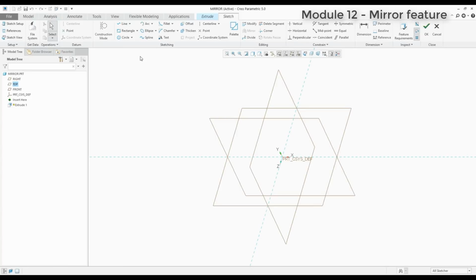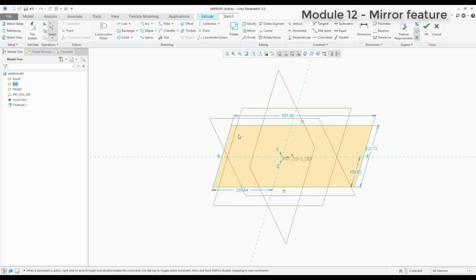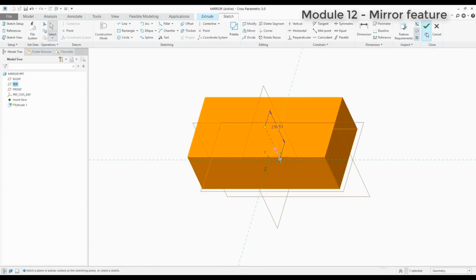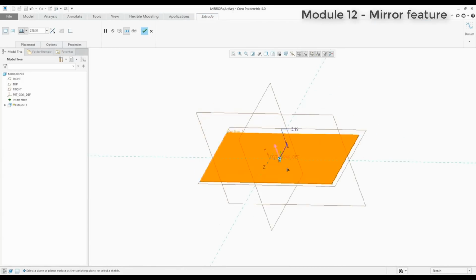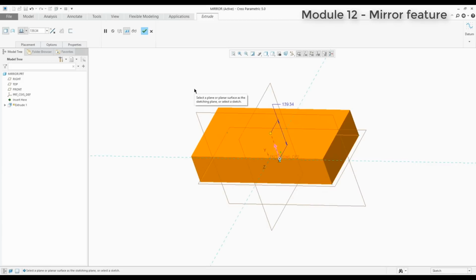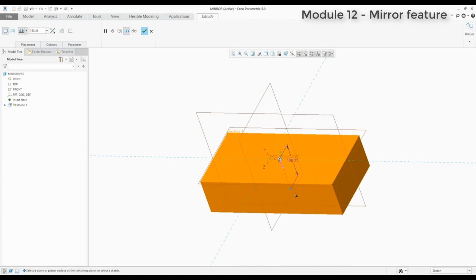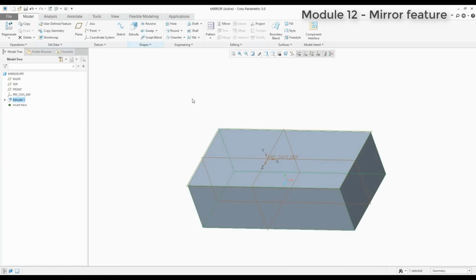If you select the sketch plane, you can directly create your custom sketch, and over here you can see that I create some base rectangle. If I finish, OK, you can see here that right now I use Creo 5, so you can see the new user interface, and the dragger is a little bit modified with visualization, and you can specify again the depth for the object and confirm OK.